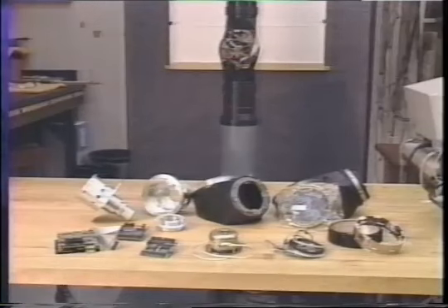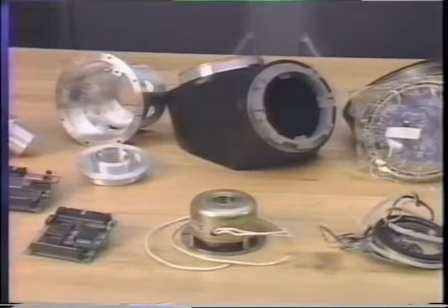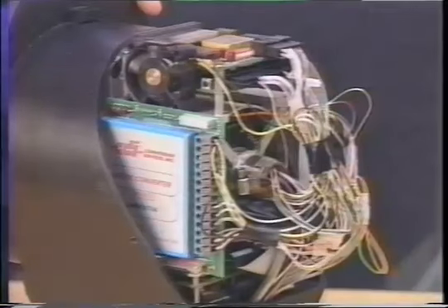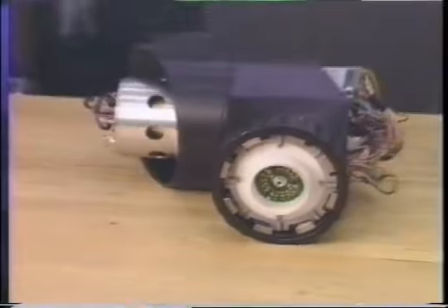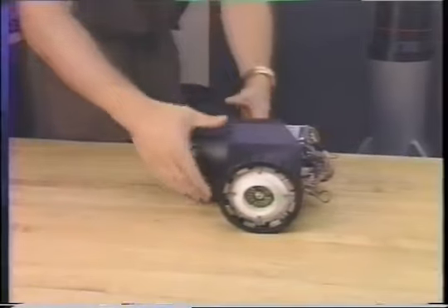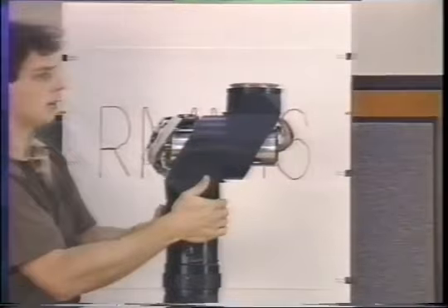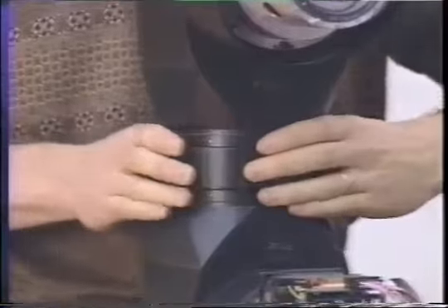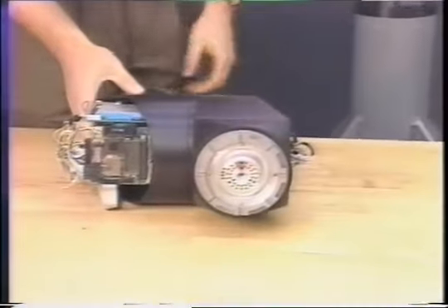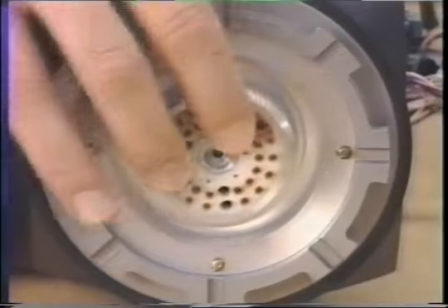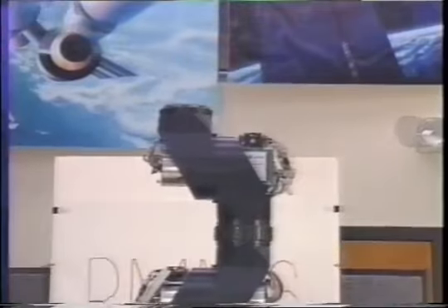Each of the modules of the RMMS is a self-contained unit which includes a microcontroller, power amplifier, sensor interface, and a communication interface. An integrated quick coupling connector allows the modules to be assembled and disassembled without using any tools. A secure mechanical connection, as well as a pneumatic and electronic connection, is achieved by turning a locking collar hand tight. The connectors also contain an LED and photodetectors to determine automatically in which of the 8 possible orientations an RMMS module has been mounted with respect to the previous module.